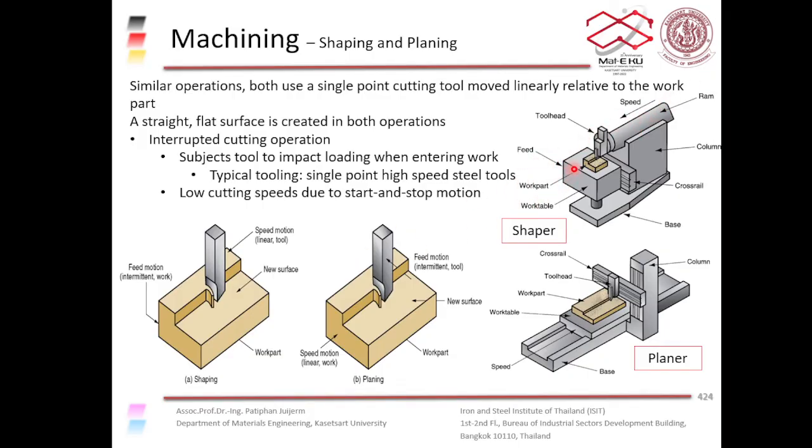So when it moves back, it will move the workpiece, we call it the feed motion. So it starts from the right hand side of the workpiece, and it will feed from, I'm sorry, it will feed from left to right, not from right to left.